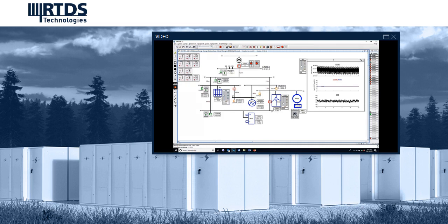If there is a reduction in the wind output, the wind speed, the battery, the diesel, and the flywheel pick up the power loss from the wind, and the microgrid supplies the loads. To reconnect the microgrid back to the main grid, a reclose signal will be issued.